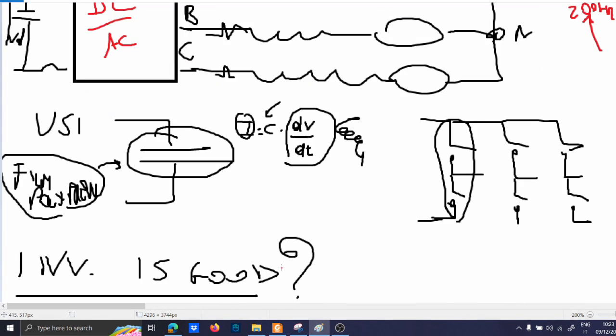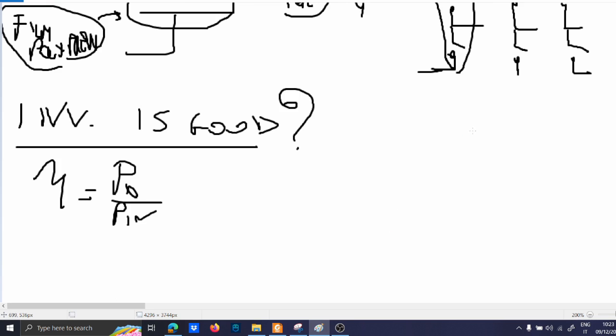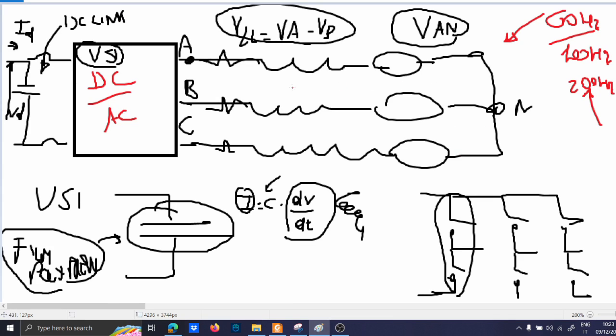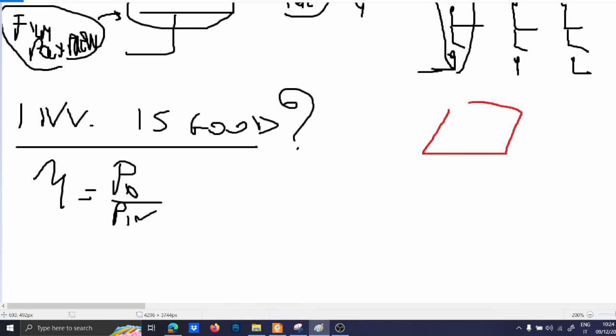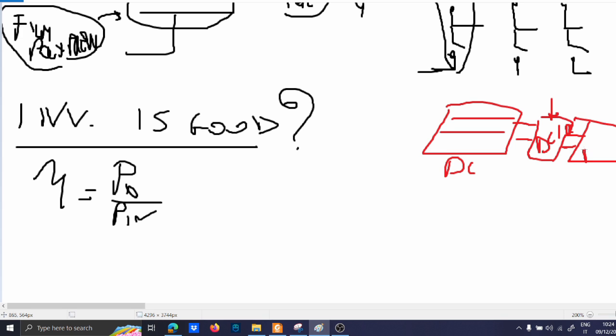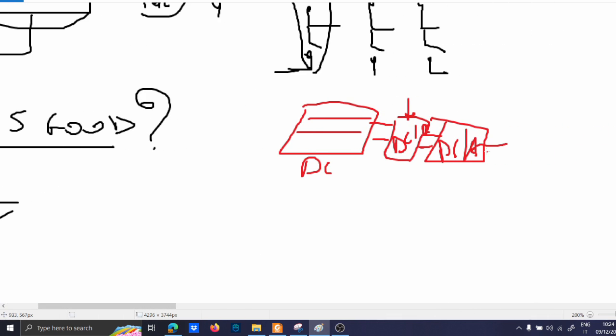And so, the thing is, you have 60 Hz components, 100 Hz components, or even the line components. So this can be even the line, the noisy line. Maybe you have a solar panel. The solar panel is DC. Then you have a DC-DC converter because you want to stabilize this, maybe a boost. And then you have an inverter, so a DC-AC. And this is fed to your house. And your house has 50 Hz, at least in Italy.